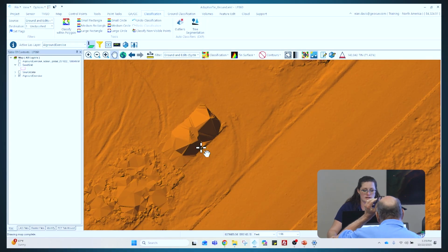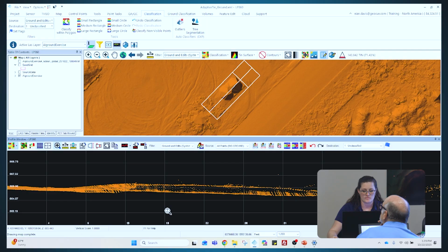Now we can also very easily see there is something here that probably shouldn't be. It's more than likely not part of my surface. So something else we saw in our previous exercise that we will also be doing throughout today, or this one, is our profile view classifier. Now to do that, I can draw straight across any object that I do not want in my class, draw a little bit wider than that object, and we can observe that feature here.